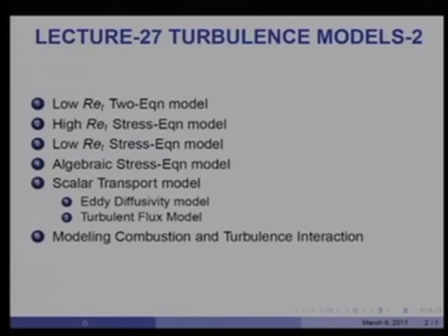And again, there are high turbulence Reynolds number stress equation models and low turbulence Reynolds number stress equation models. Computationally, these two turn out to be quite expensive, and therefore, a shortcut approach is often adopted. It is called the algebraic stress equation model.